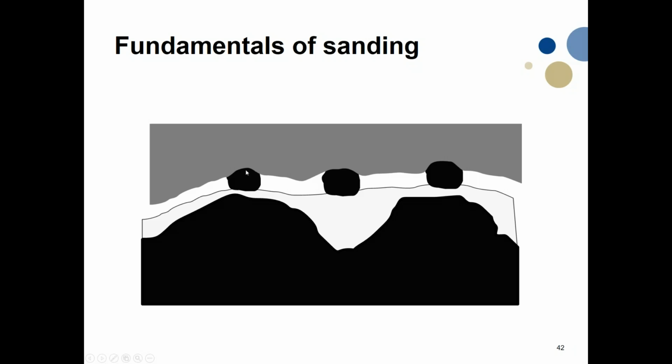And since there's quite good roughness or grip between the sand particle and the rubber, typically those particles tend to be dragged with the rubber if the rubber starts to slide, and then the particle starts to slide over the snow and starts to plow into the snow or ice layer. And that gives better friction than if there was direct contact between the rubber and the snow. So some countries still allow studded tires, and for sanding and studded tires, the physics is pretty much the same. We have a localized hard particle under the tire that can scrape and plow into the snow layer.